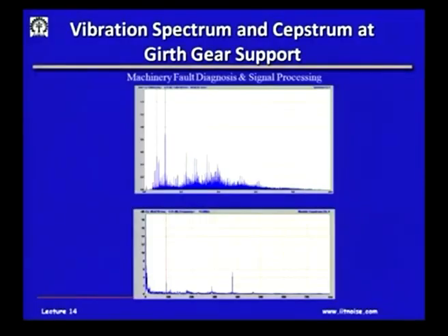So, if I was to go back again to the vibration spectrum of the girth gear support, this is how it is. The real world signal is full of so many frequencies, because this is the frequency domain. It becomes very difficult to identify whether it is this frequency and so on. But once you do the Cepstrum, you will see the important group of frequencies getting clustered into these Q frequencies.